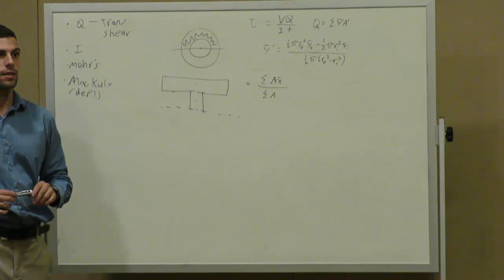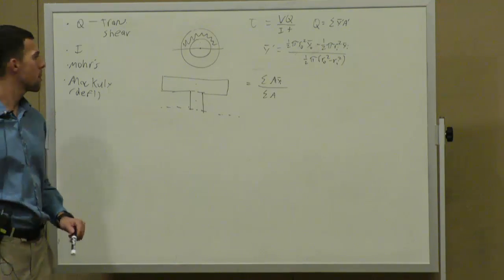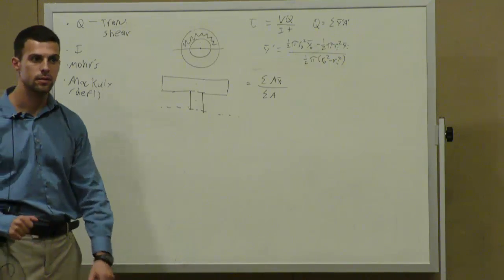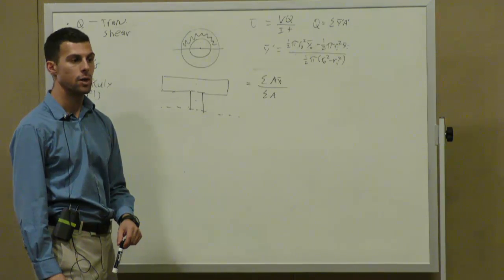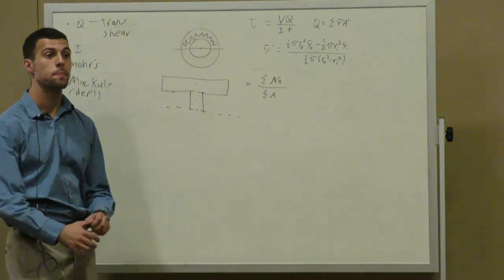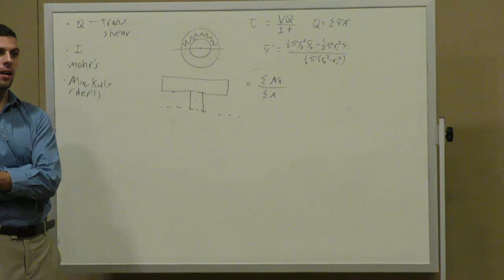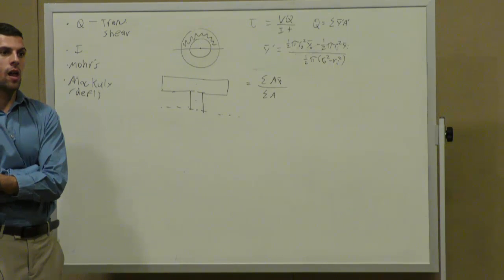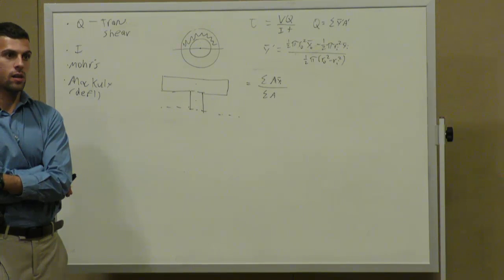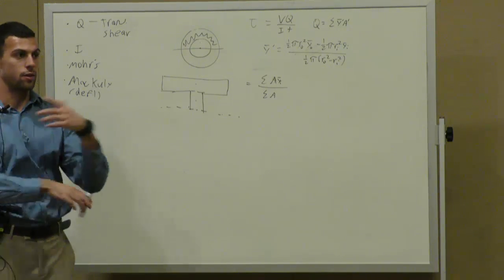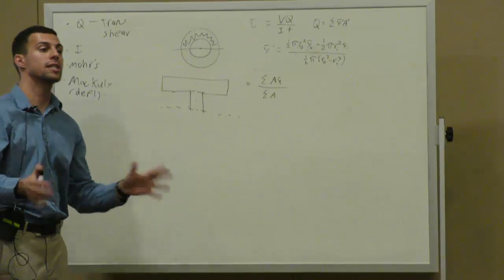Yes? Let's say on my previous exam, we had an I-beam, but the bottom was smaller than the top. Yuck. When you're finding the y bars, it depends on what the point is. Do you take the lower half or the top half? No. You just take the half that you care about.